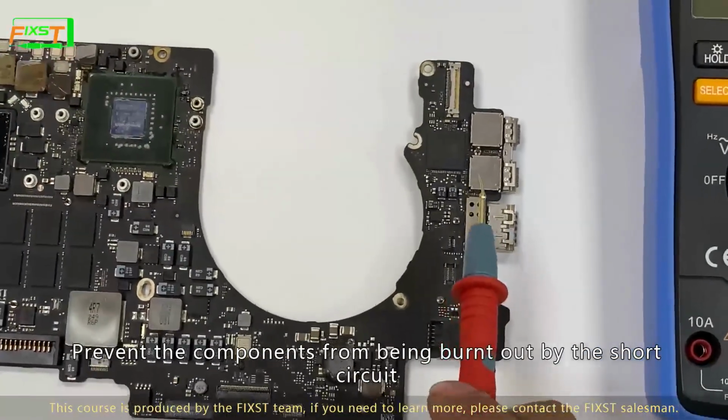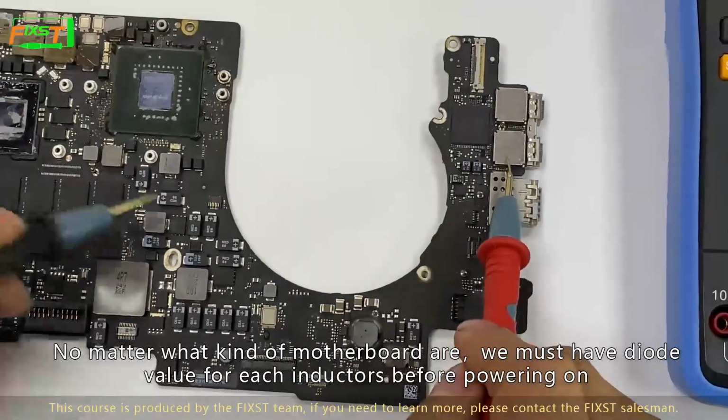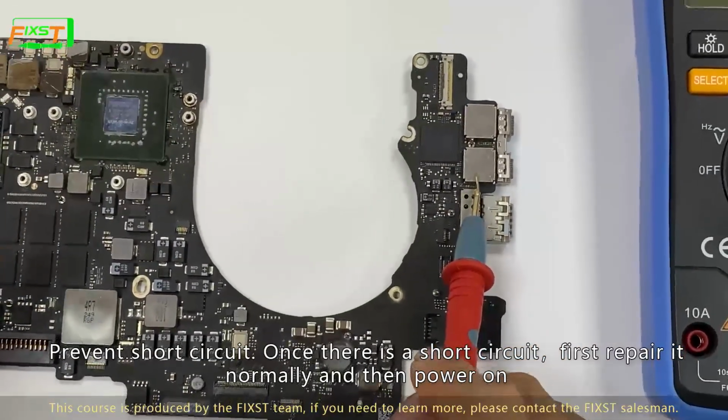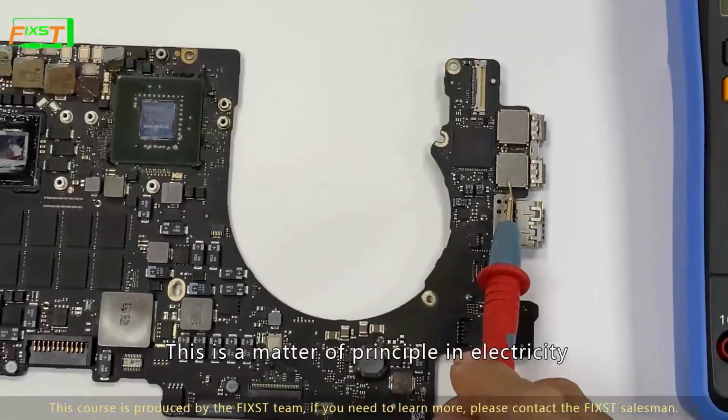Prevent the component from being burned out by a short circuit. No matter what kind of motherboard it is, we must check the diode value of each inductor before powering on, to prevent a short circuit. Once there is a short circuit, first repair it normally and then power on. This is a matter of principle in electricity.